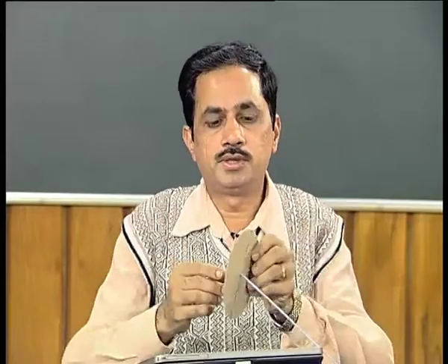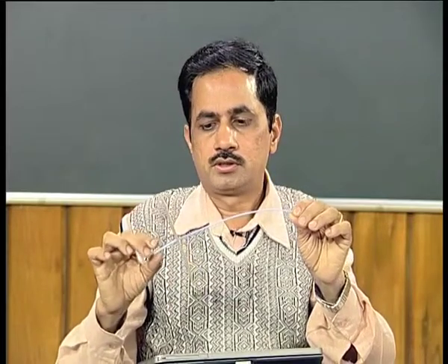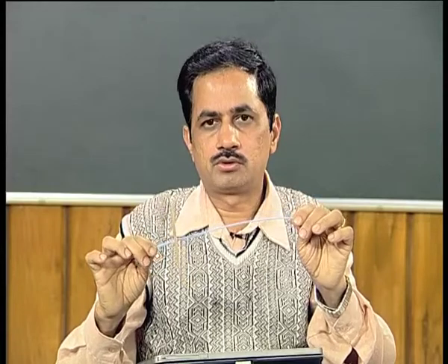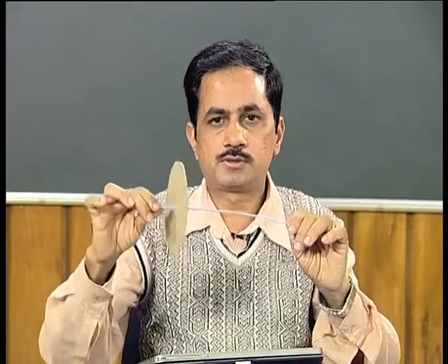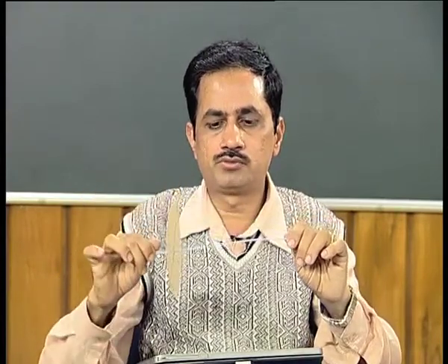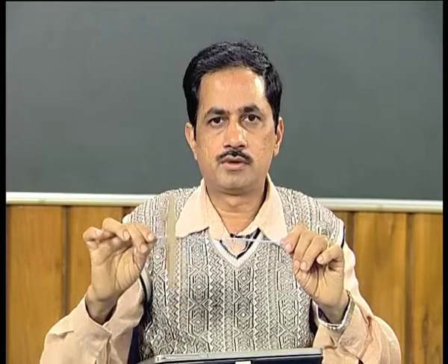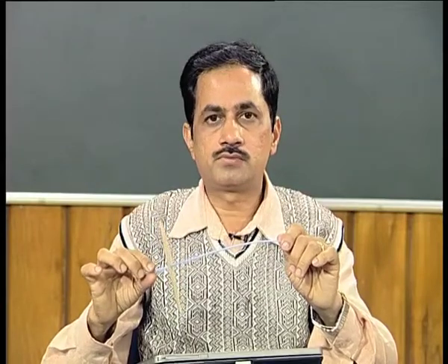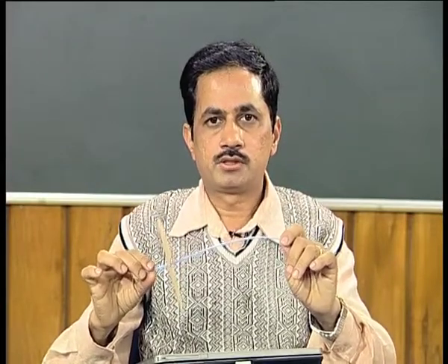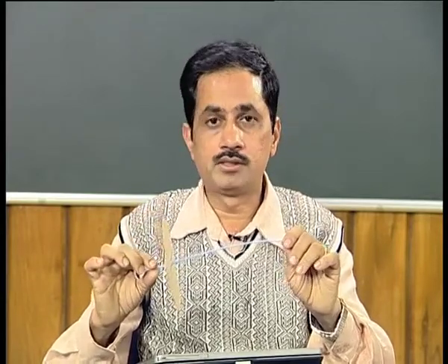So, for the present case we will be considering a cantilever beam like this, and this shaft will not only be spinning about its own axis, it will also be whirling, and this is the whirling motion. So, spinning and whirling both will take place, and in this case we will consider the spin and the whirl frequency different, and we will try to see how this whirl frequency changes with the speed. In this particular case again we will not consider that there is unbalance in the rotor.